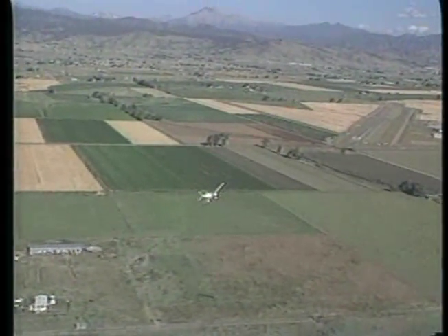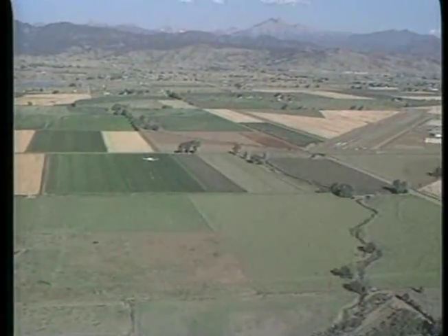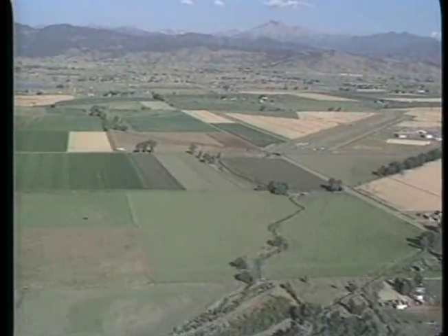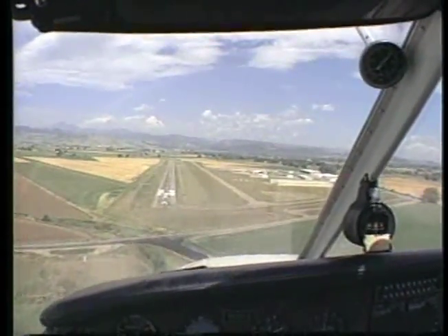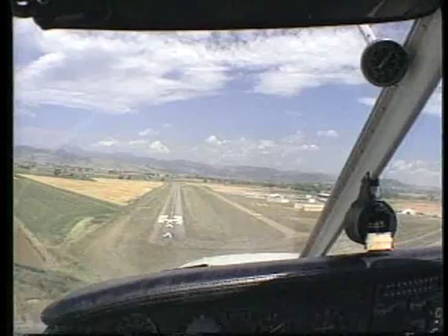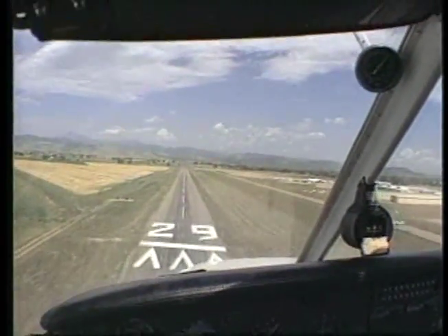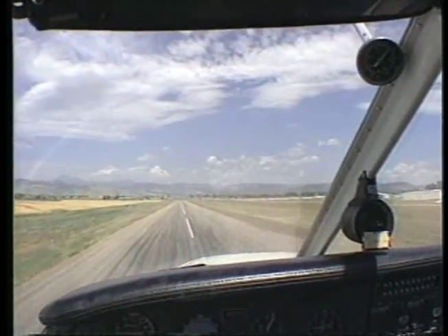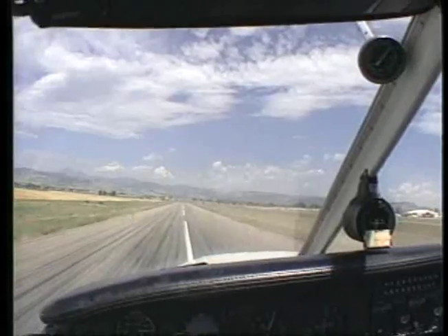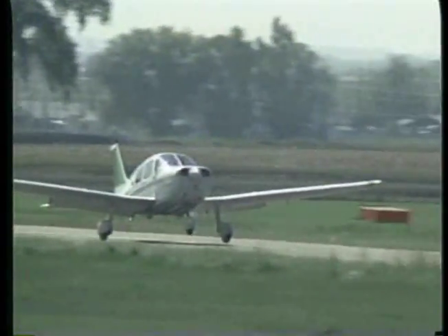Reduce the airspeed progressively to that recommended by the manufacturer for short field landings. Ideally, you should conduct the final approach at a constant glide angle, airspeed, and power setting. You may need to make minor adjustments to pitch and power to maintain a stabilized approach. If you maintain the proper approach configuration, the airplane will not float above the runway and you will touch down close to the stall speed.